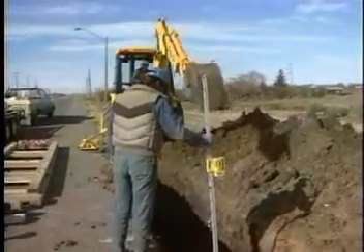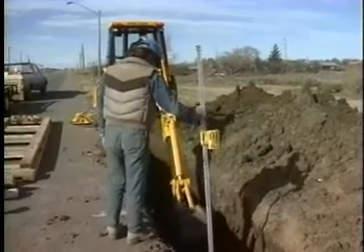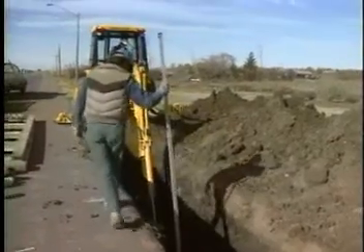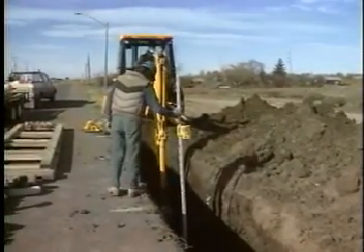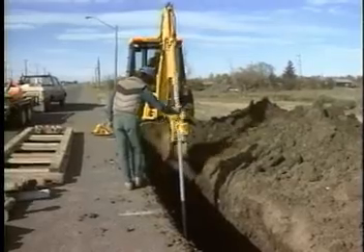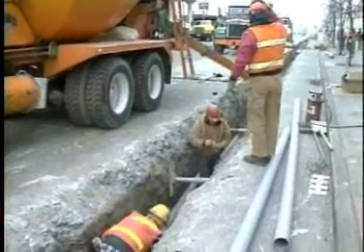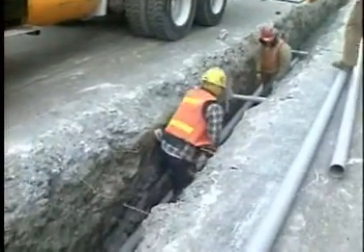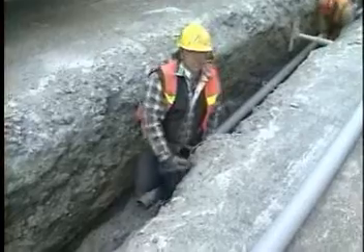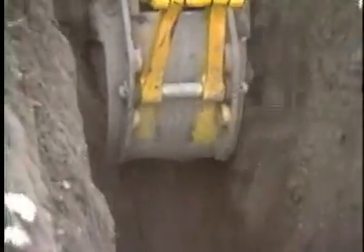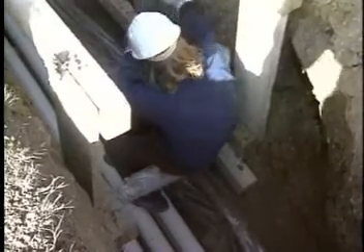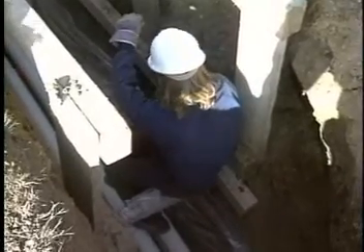If trenching is selected as the placement technique, the grade of the trench bottom must be determined. If the ground is reasonably level, the trench should drain in both directions from the center at a rate of 7.5 centimeters per 30 meters. The depth of the trench must provide for the minimum cover required and must be wide enough for the conduit formation plus a working space for construction. The sides of the trench, especially in loose or fluid soils, should be sloped. Where the trench is deeper than 1.5 meters, shoring safeguards are required.